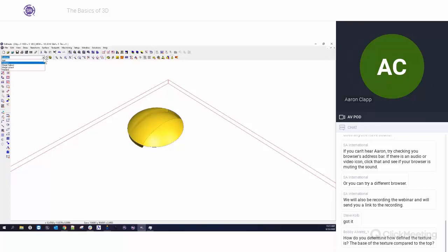So let's take a look at the next one. The next one is going to be merge highest. Now these are the ones that get a little complicated. So what happens is on merge highest, it takes a look at both of the reliefs and says, okay, where is the highest point in all of these different reliefs? So what it says is, okay, well, in this case, from here on, the dome is higher. And so I'm going to use the dome as my relief.